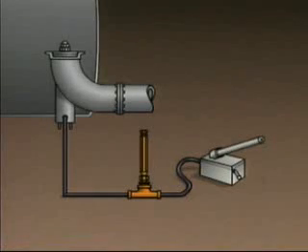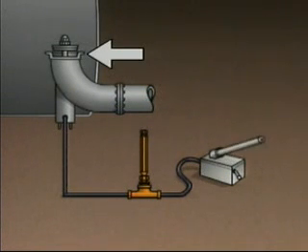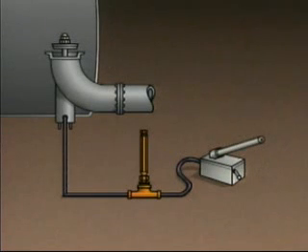Another feature that many tank trucks have is an internal safety valve located in the product outlet. Its purpose is to prevent product from flowing through the product outlet during an accident or emergency. In the arrangement illustrated here, a hydraulic pump has to be used to manually open the internal safety valve during normal unloading operations. But the valve is also designed to close automatically if there's an accident or emergency.